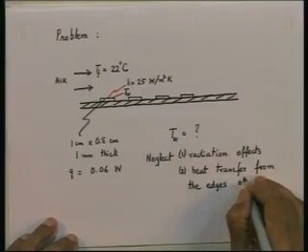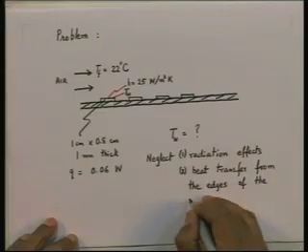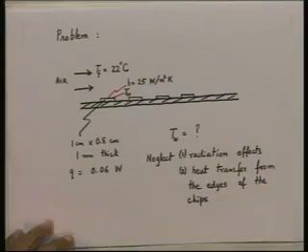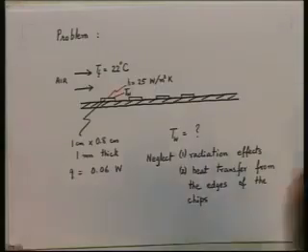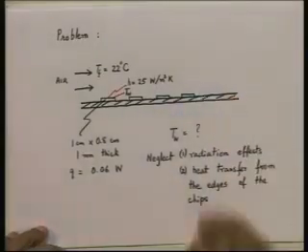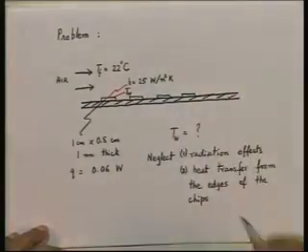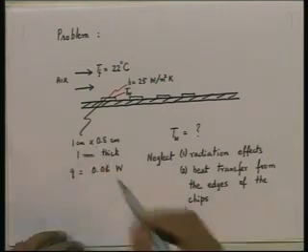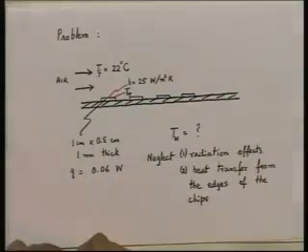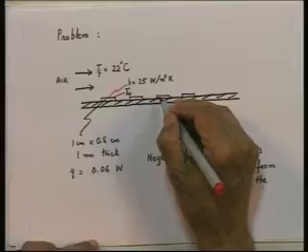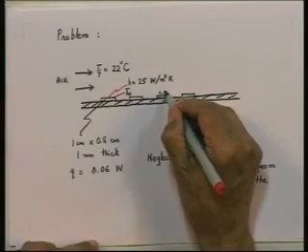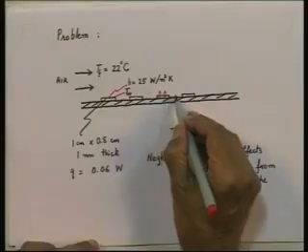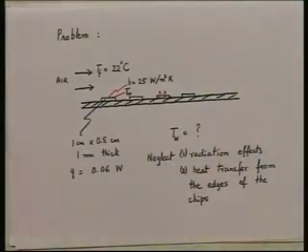From the edges of the chips. All right, these are the edges, the 1 millimeter thickness all round. So, assume that all the heat that is being generated is flowing out by convection through the 1 centimeter by 0.8 centimeter face. That means all the heat is flowing out like this. Neglect any heat flowing out through the edges and neglect radiation effects. This is for simplifying the problem.